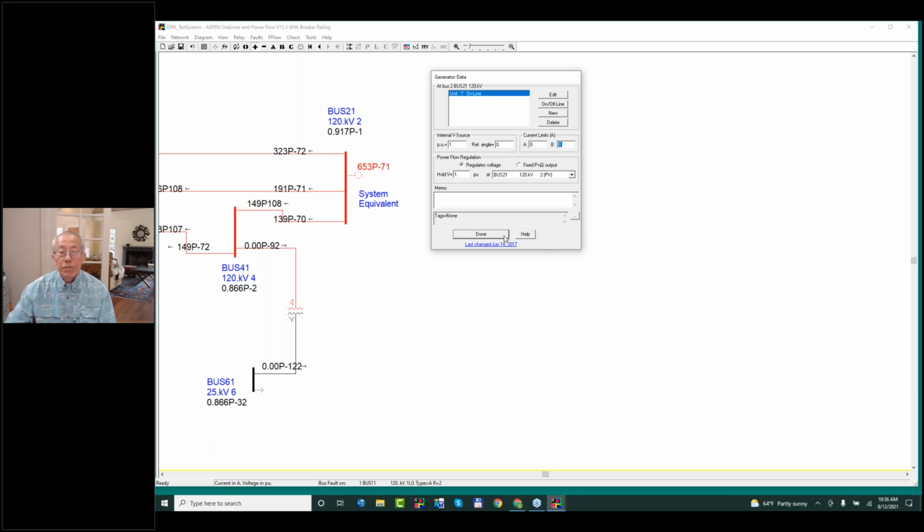Now we had no clue how to limit the current, because we didn't understand at that time how any of these things work. So we said, well, we know how to limit the current, kind of. And one of the ways is that, knowing the synchronous machine is represented by a voltage source behind an impedance, all we have to do is lower that internal voltage source. I'm not going to go into it. When it's a single line to ground fault, it gets more complicated because you've got negative sequence and zero sequence current. But just think of the 3-phase case. We would simply lower the voltage behind the impedance. So that's what we did.